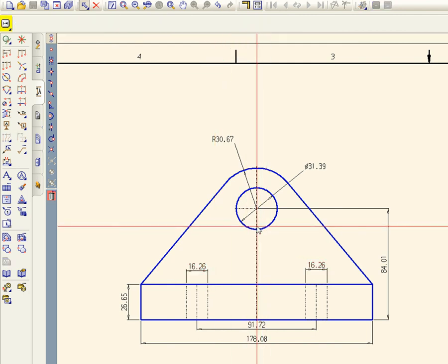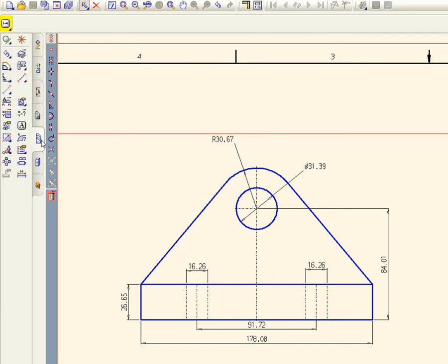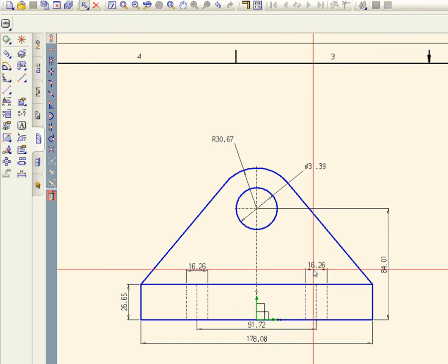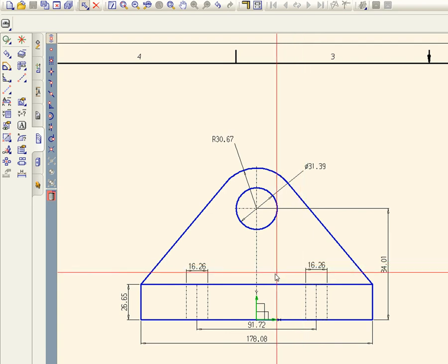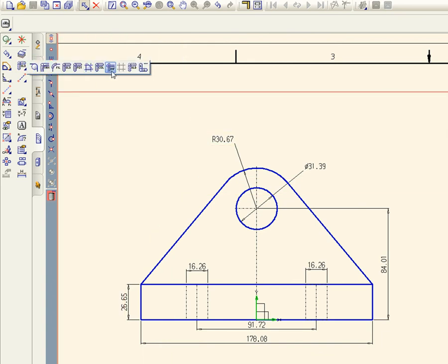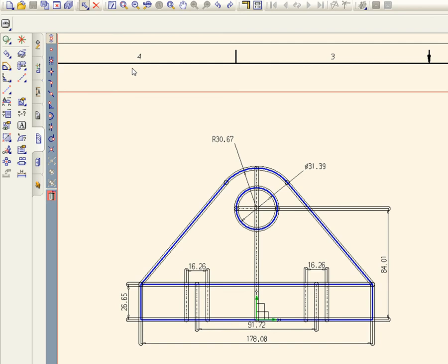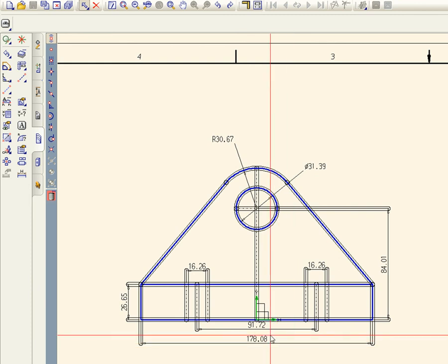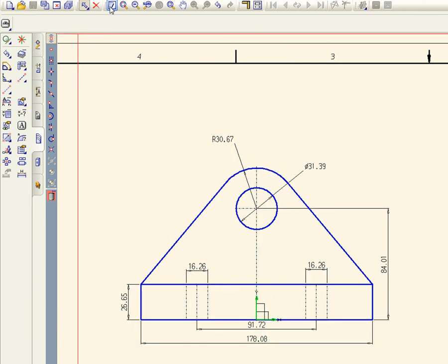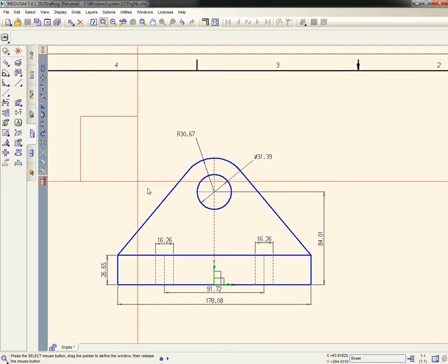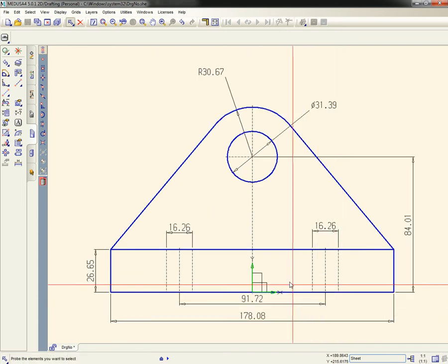Now a quick introduction to MEDUSA4 Parametrics. For that I choose the Parametric tool tray and I select the Prim button to set a prim as a reference point in the drawing. I've already got most of the building blocks for a parametric design, so I'll just quickly test the design by clicking on this icon here, and yes indeed, MEDUSA4 Parametrics recognizes all of the geometry. So this means I've created a template drawing which I can save, open, edit, and then use as a new drawing as required. I can make changes to dimensions just by modifying the dimension text, for example.